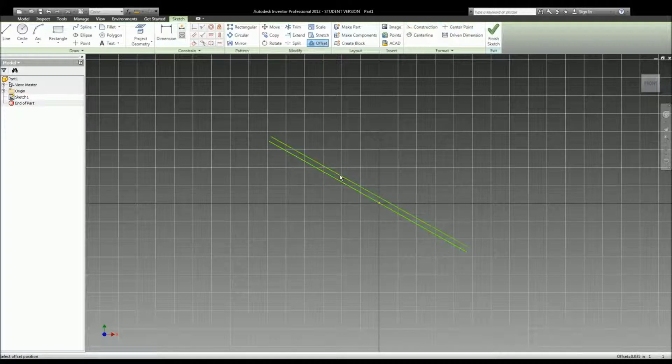I'm going to click this line and see, right now it's constrained, which is one of the words here. What constrained means is it's limited to the specific direction that we are on right now, which is basically the quote unquote face of this line. But you can see that I can move it away a specific distance. I'm going to click, and that's what the offset function does.